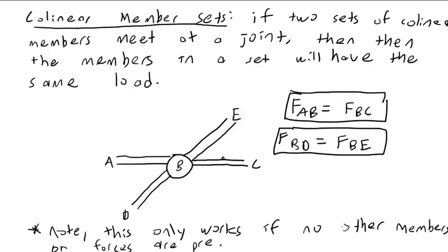See, the entire theoretical foundation of this is, imagine I were to sum forces on an axis perpendicular to member AC. I would see that these would have a vertical component, and these would not. So if I had an x prime and a y prime axis, if I summed about the y prime axis, these would have a component here, but these would not.